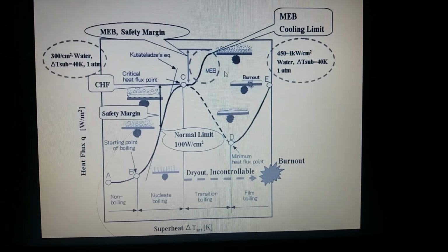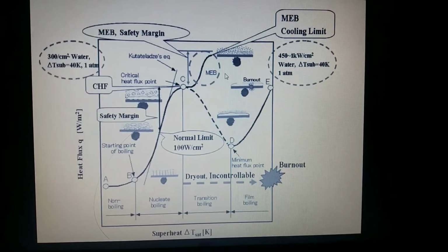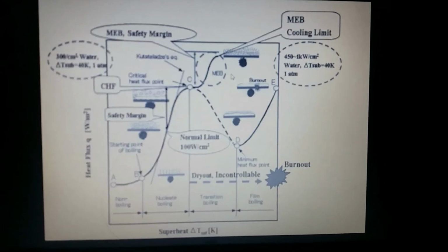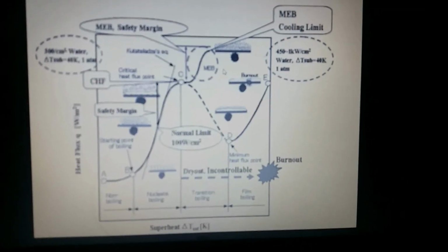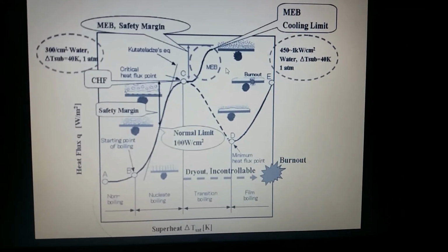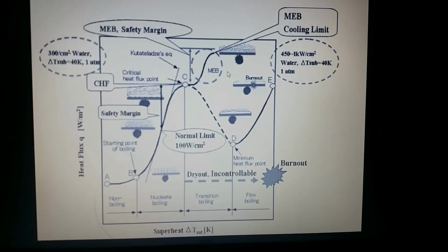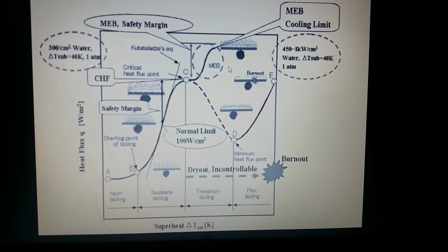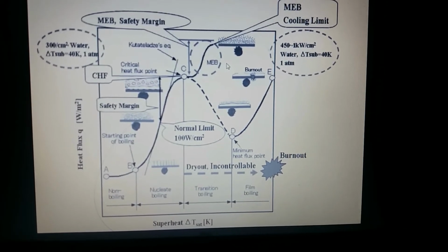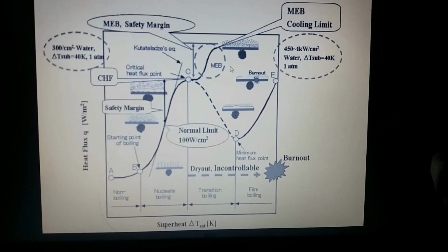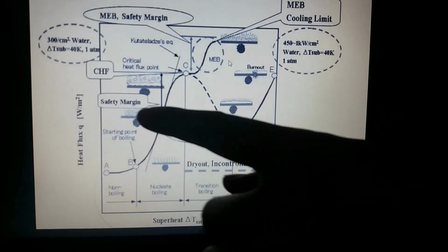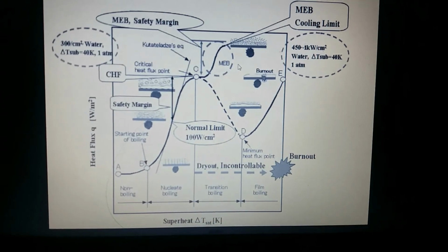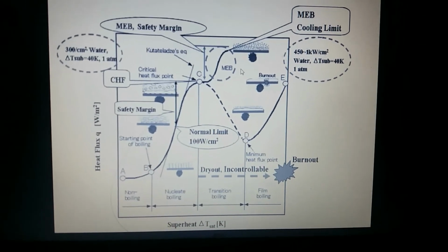Boiling heat transfer is well known as a superior heat transfer technology to remove a large amount of heat from a hot body using the transport of latent heat with a phase change. However, there are some difficulties with applying this cooling method to electronics. The heating surface becomes covered with coalescing bubbles at the critical heat flux, the maximum of nucleate boiling, where the liquid is not fully in contact with the heating surface.